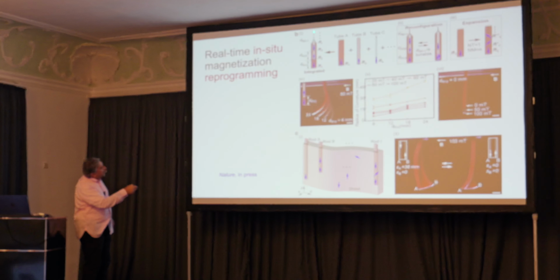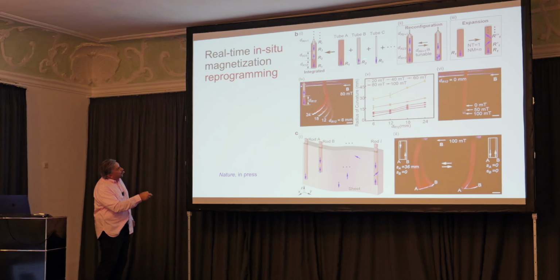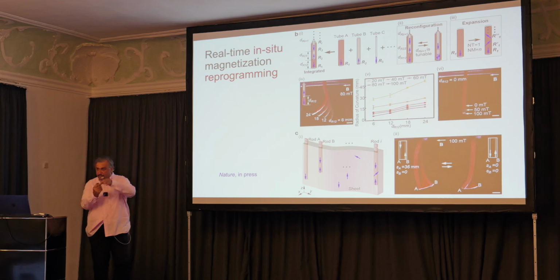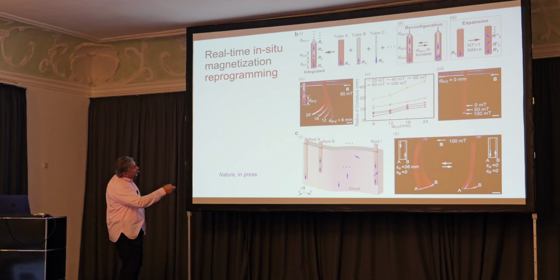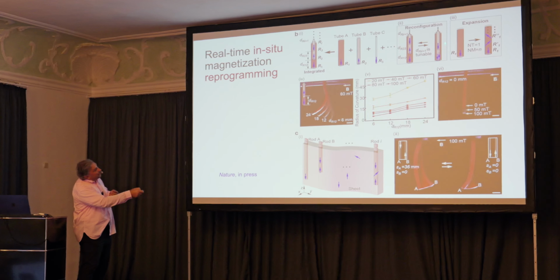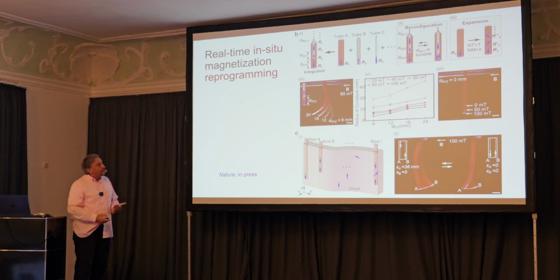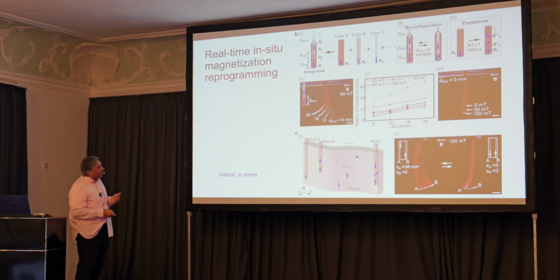So we make these, in this case, concentric tubes. Each tube has a magnetic profile, which could be simple in this case, just horizontal, downward, upward, downward, with different magnitudes. And each tube can be concentric, and we can actuate them concentrically. This can be done with tendons in robotics, so that by changing the relative position of each tube, we can reconfigure the magnetic profile completely. If we do this effectively, the total magnetization is 0, so the same tube suddenly turns non-magnetic, or by having different modes, and you can even have a different number of tubes together.